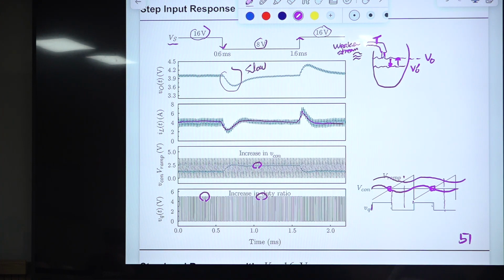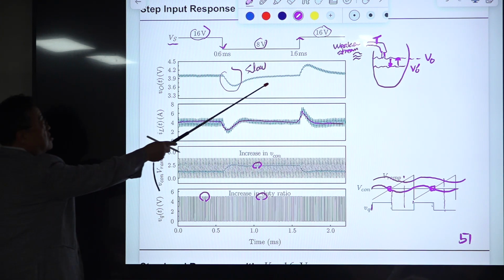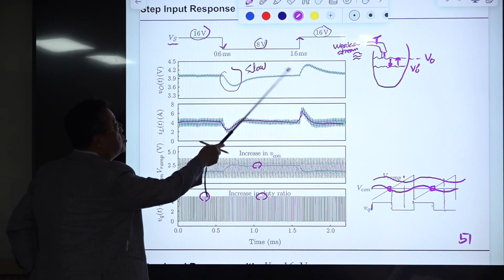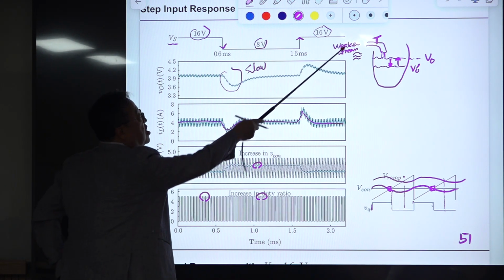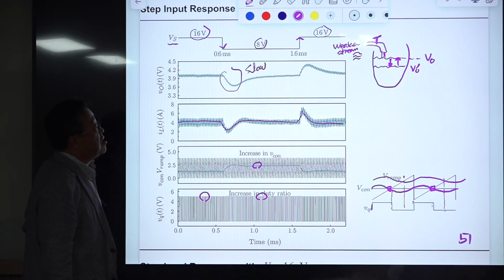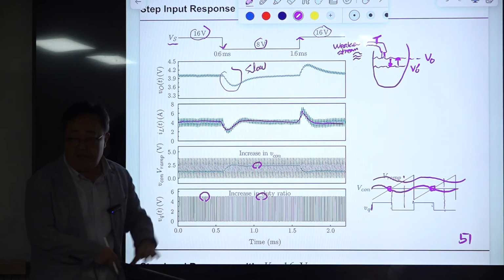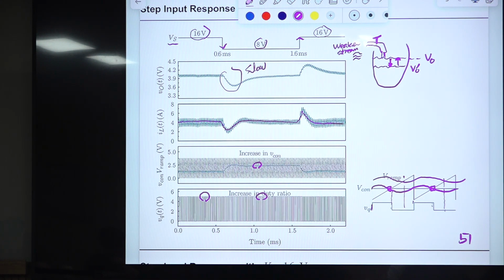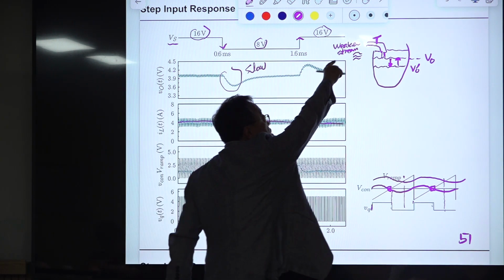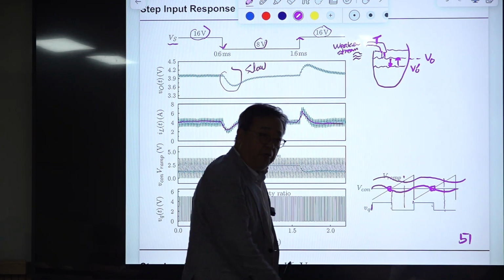Okay, so you reach this, and all of a sudden you increase this water stream strength. Then to maintain the same level, during the short transient period, the water level will be increased like that. Then the controller turns this faucet in the clockwise direction.